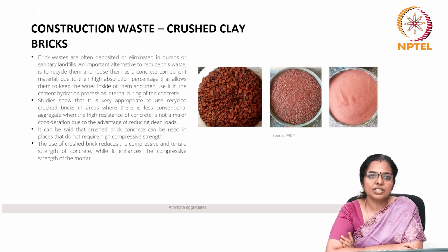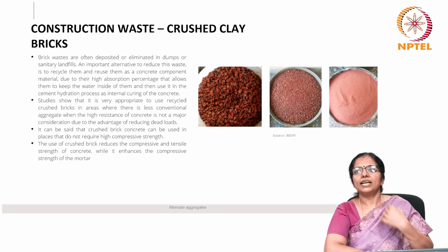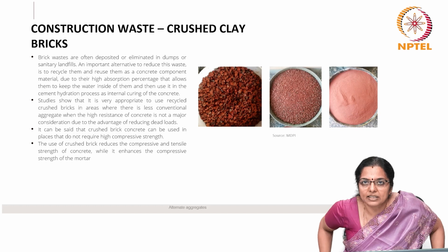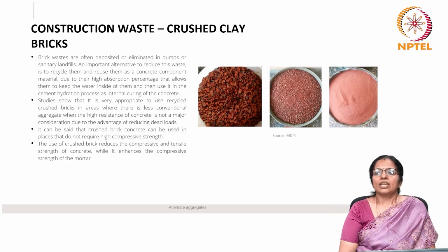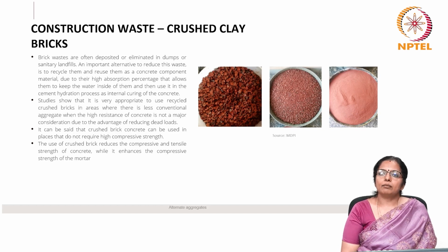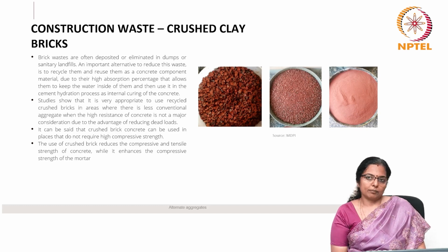Let us look at crushed clay bricks as an alternative. Brick wastes are often deposited or eliminated in dumps or sanitary landfills. It's an important alternative to reduce this waste, and one of the ways is to recycle them and reuse them as a concrete component material. Due to their high absorption percentage that allows them to keep the water inside of them and then use it in the cement hydration process as internal curing of the concrete, they are found to be suitable.